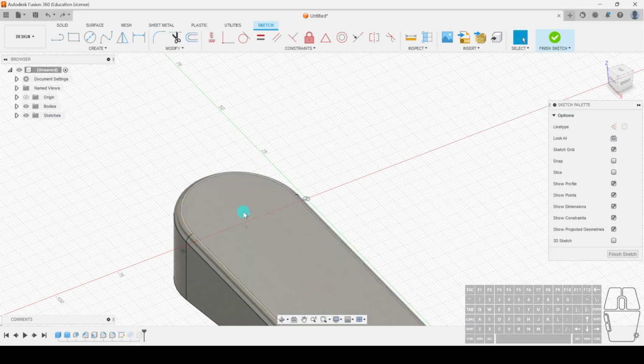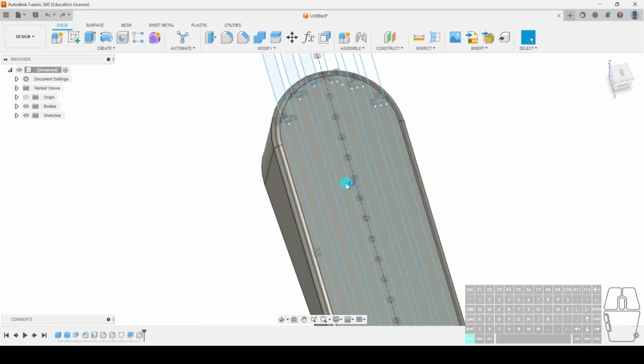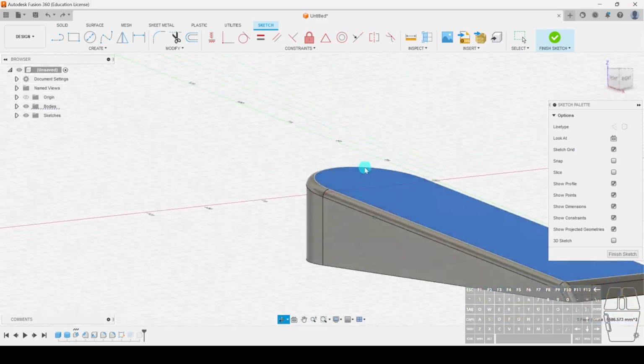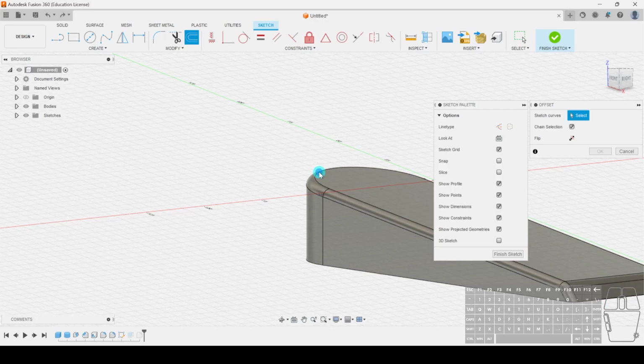So even though you've put it on the face, you've selected this face, you've got a sketch, and you try to offset, you can't offset. Think of it, why isn't it letting you offset? What is a fundamental idea of sketches? They basically make bodies. So once the body is made, it's like a piece of paper, right?